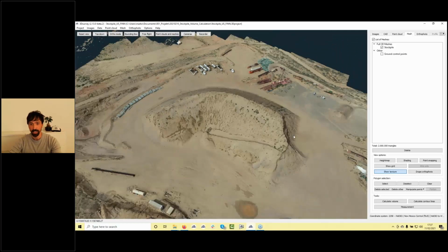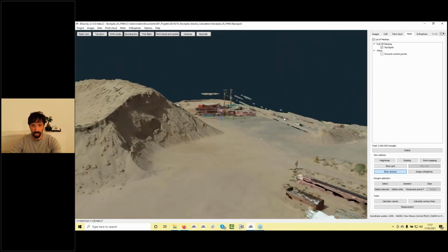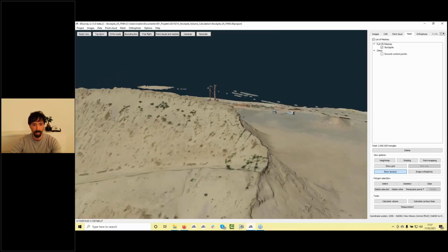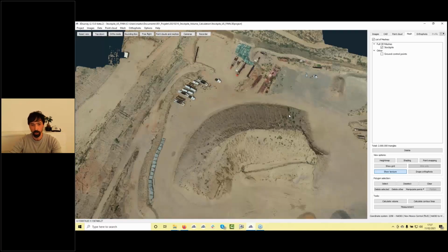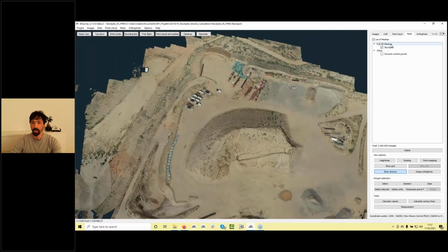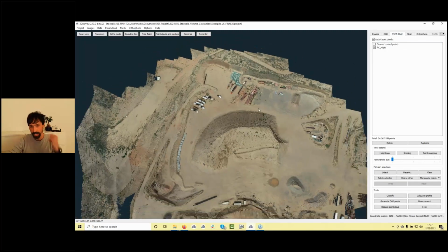Why? Because in a full 3D mesh, you can maybe get some kind of balloons like in cables here. This can happen if there is high grass or something like that. Of course, it also works if you would like to calculate it, but we advise you to turn off the full 3D mesh, go back to the point cloud and calculate a regular grid mesh.